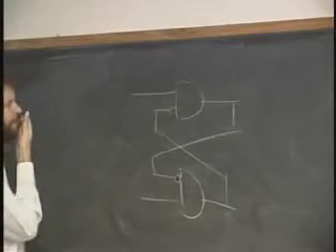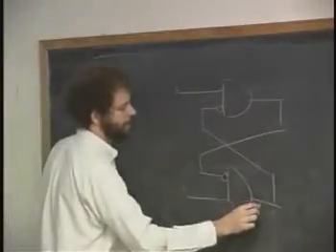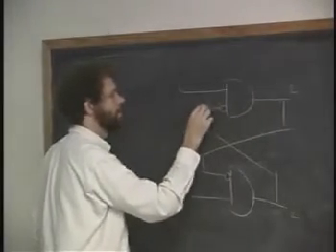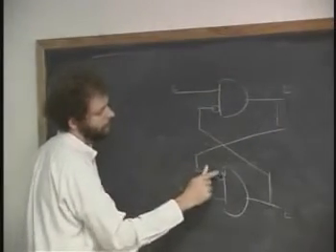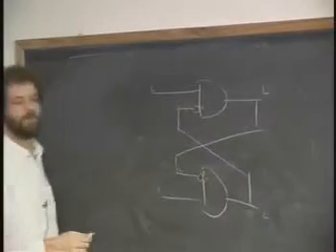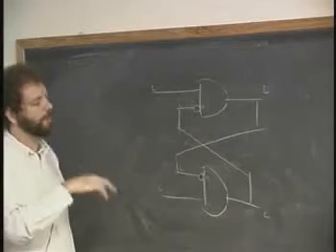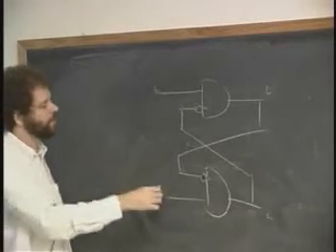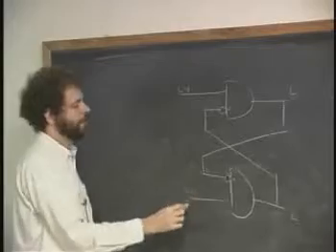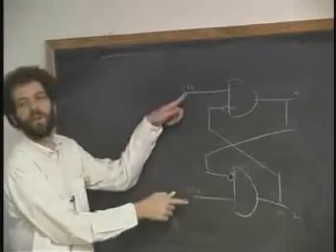Okay, so we said we're going to start out with both of these things being low. Low, and the output from here we said was going to be low. This is going to be low, and this is going to be low over here. Okay, and this gets inverted on the inside to become high. Okay, now both of them are going to go high at the same time. And just taking an extremely crude model of time, where time is just going to go in steps with the letters on the board, let's say they both go high at the same time. Okay, what's the output of both of these AND gates if both of these go high at the same time?